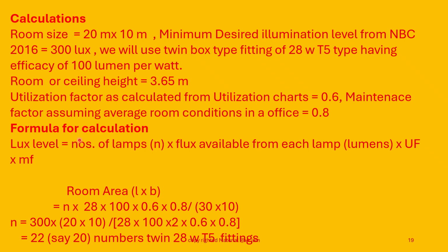The formula for calculation is lux level equal to number of lamps multiplied by flux available from each lamp in lumens multiplied by utilization factor multiplied by maintenance factor.